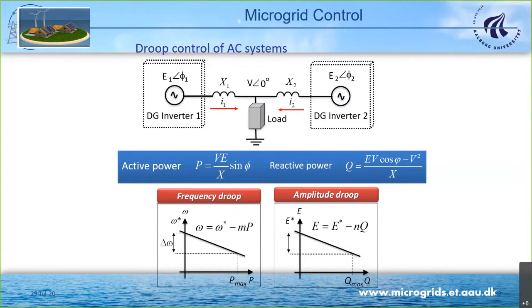One of the best solutions that I think big electric systems give us intrinsically is the use of synchronous generators. When we use synchronous generators, they are normally coupled, and they can be synchronized without any kind of communication between them across a country. And this is amazing. How we do that is just by using what we call the frequency droop control. So you may know that with a synchronous generator, when you increase the power, the speed is reduced. That means that the frequency is also reduced.